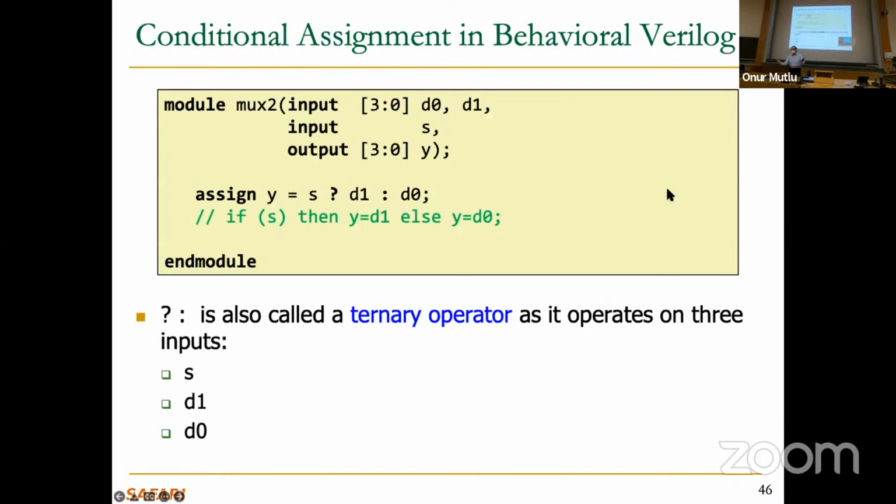Again, you will get used to it. It's always kind of odd, in my opinion, to describe a programming language and how it works, because in the end you're going to write code in it, and you're going to learn it much better by writing code. Okay, conditional assignments. Again, this is not behavioral. This is a MUX described conditionally. It's a 2-to-1 MUX, but each input is 4 bits, except for the select, of course, because select depends on the M value in the N-to-1 MUX.